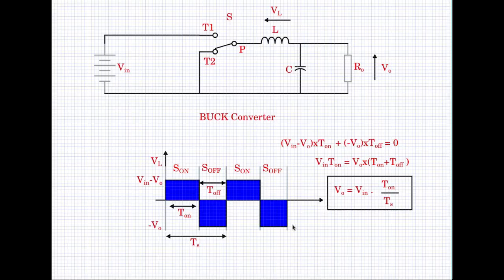This is just as an example. I thought I will mention this to you, the importance of the volt second balance of the inductor. Whatever may be the converter, if you take the volt second balance relationship of the inductor, you will get the input output relationship. This is the key concept that I want to convey in this particular video lecture.